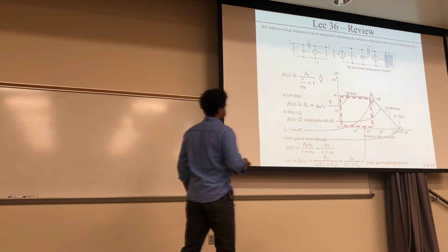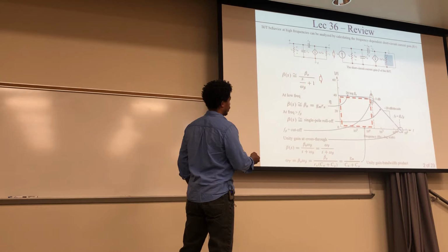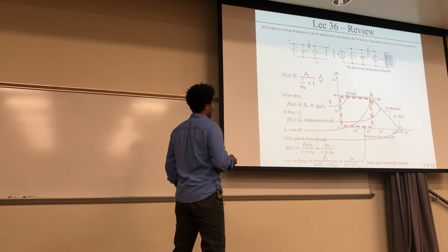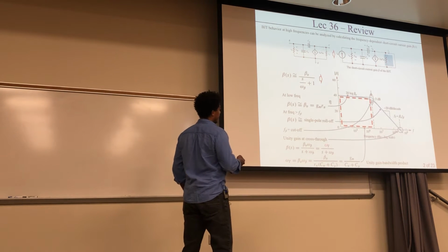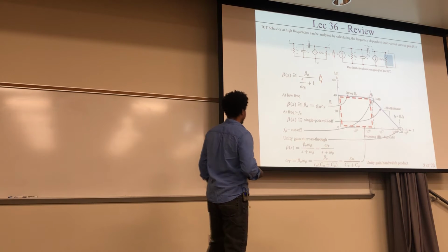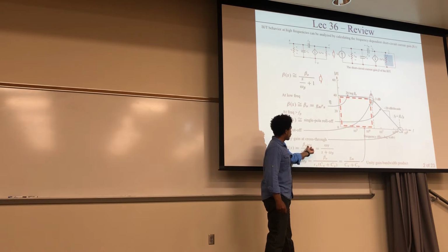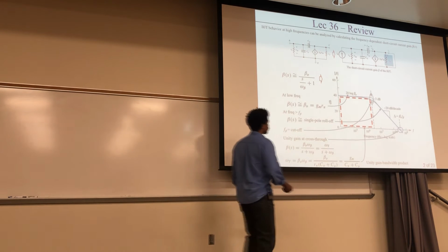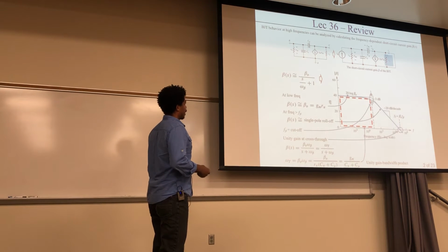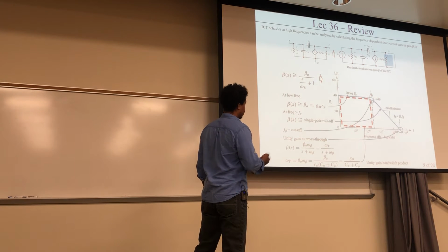The unity gain is where this keeps going down and crosses through 0 decibels. Omega T is the unity gain bandwidth product, and it is just your beta 0 multiplied by your cutoff frequency, omega beta.